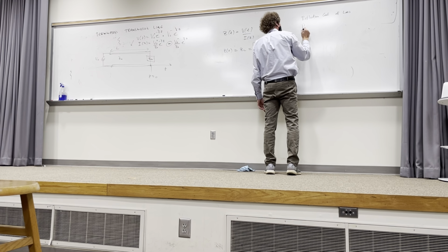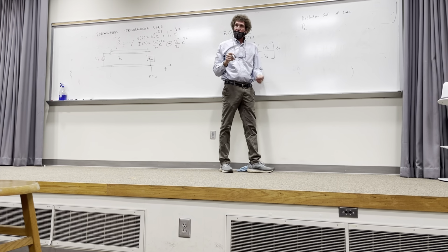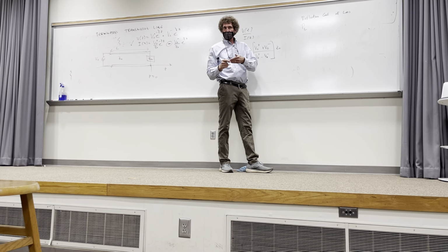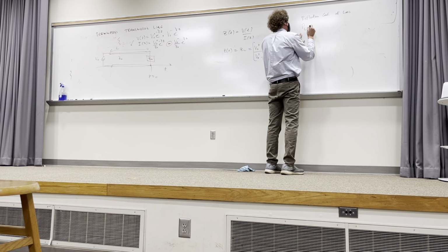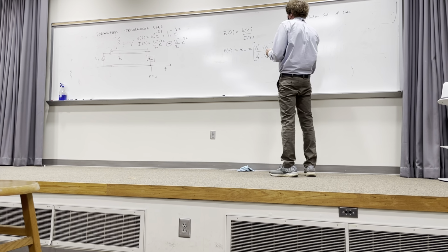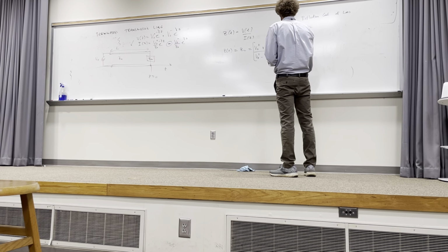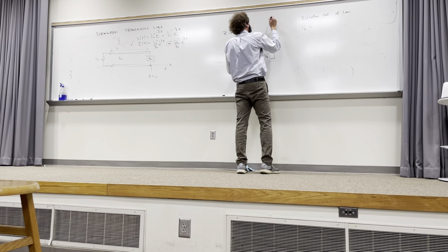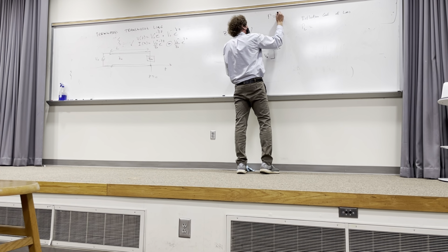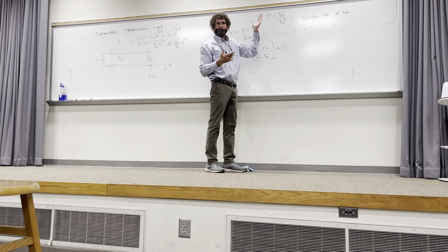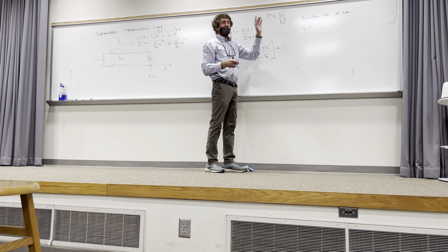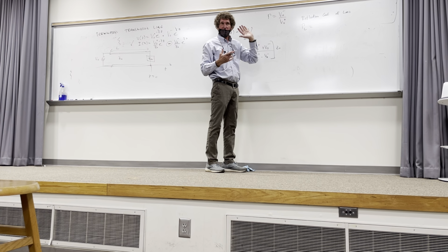And we use the term gamma sub L. Gamma is always a reflection coefficient. Sub L just indicates it's the reflection coefficient at the load, where the load is attached. And that is the ratio. Let me define the reflection coefficient in general. The general definition is V0 minus over V0 plus, but it can be at different points, so these two may vary versus position. Just go along with that for now. I'll try to expound on it in a second.